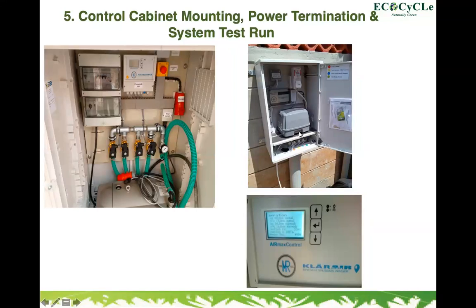On the far left, we have another, bigger one that is used for a bigger system. Those things you see above that compressor are responsible for the application of air into the aerator disc. From the far left, we have the pipe responsible for filling. That is when the PLC signals, it fills the sewage from the buffer chamber to the treatment chamber. The second one is responsible for aeration, the application of air into the aerator disc for the process of aeration.